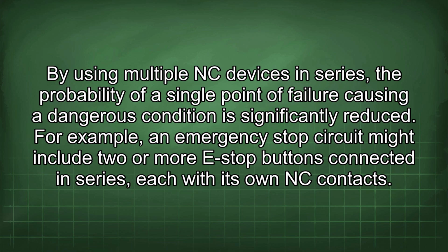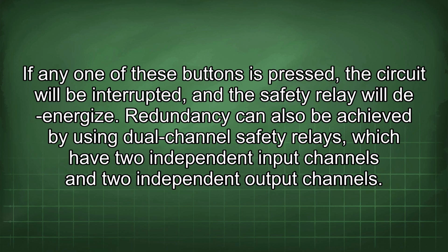For example, an emergency stop circuit might include 2 or more e-stop buttons connected in series, each with its own NC contacts. If any one of these buttons is pressed, the circuit will be interrupted, and the safety relay will de-energize.